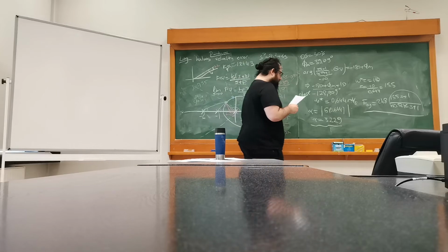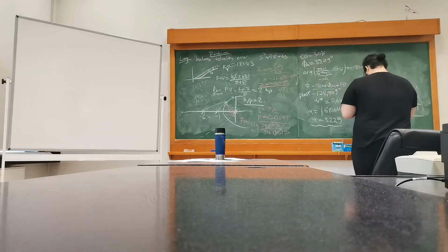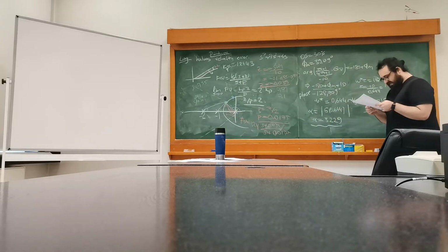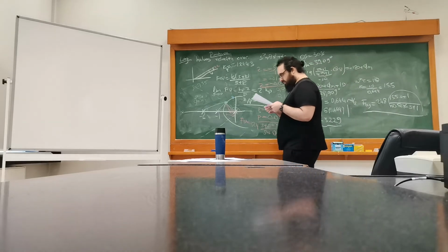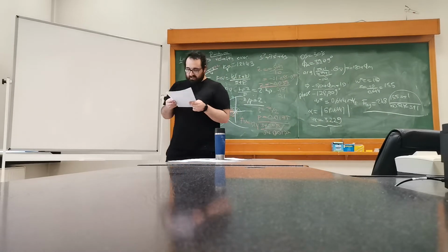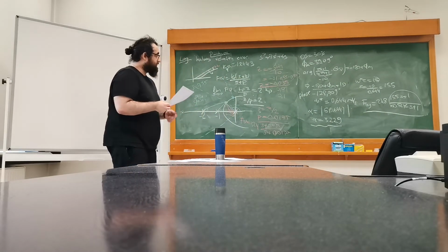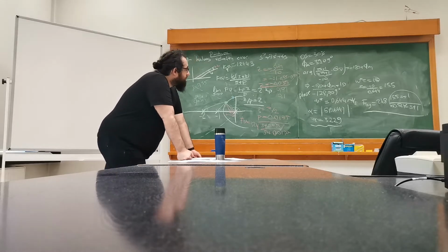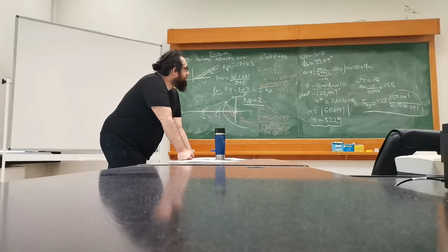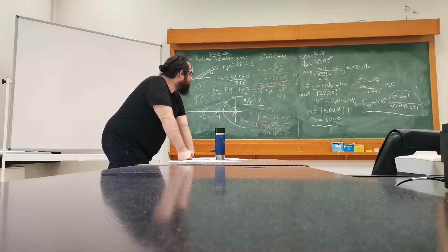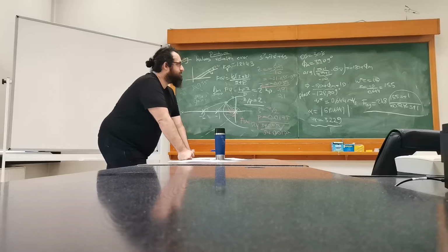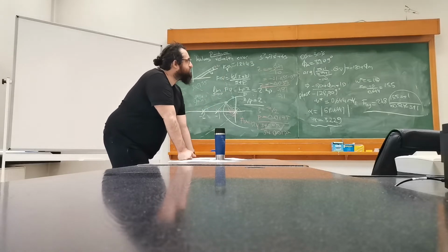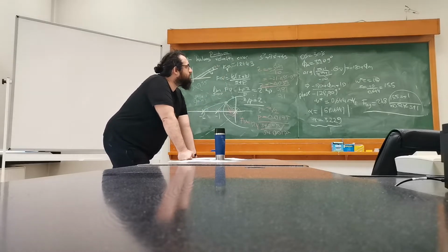Now, I didn't convert it, but you can look up where the zeros and poles are and see if they're really close or not. But they don't really have to be the same, because we are choosing it based on the ratio here and a certain angle condition. Therefore, they might not match, but their response should be close to each other.